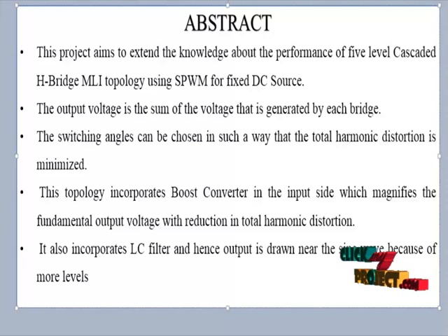High power efficiency is obtained from the slow biasing of the high bridge power supply terminals allowed by a particular arrangement and control of two complementary active neutral point clamped voltage source converters, which results in the main PWM switching voltage as well as the maximum drain source voltage VDSS of related transistors being reduced to one half of the input VDD voltage. This product introduces the main concept of the floating H-bridge topology and presents in detail the circuit realization.